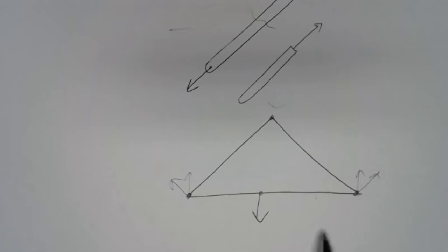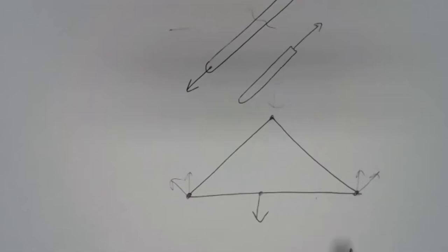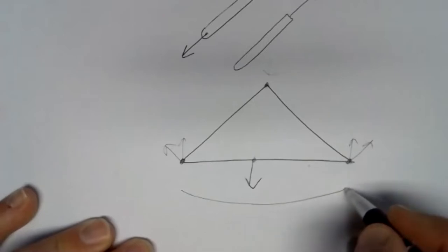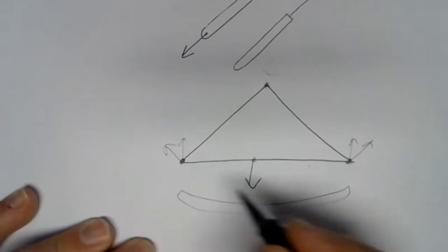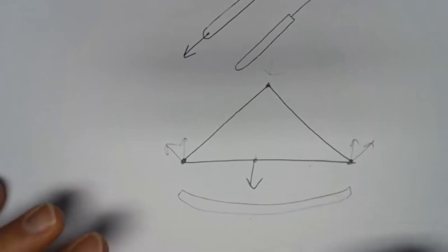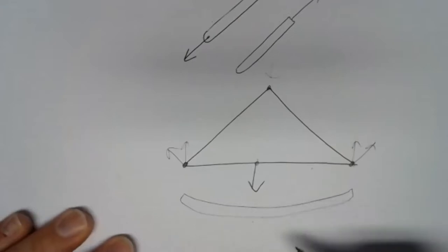When we loaded up a truss, if the forces are only at the ends, only at the joints, then each member is either in tension or in compression if it's got a load on it. Well, a member like this isn't in tension or compression, it's in bending. If we were to apply this load, if this was a very heavy load, we'd expect the member to kind of do that, to kind of bend. And bending is a combination of tension and compression, where you've got tension on one side and compression on another. So in frames, we allow for bending to be a possibility, and that makes life all sorts of complex if we really want to figure out what's going on in the members.